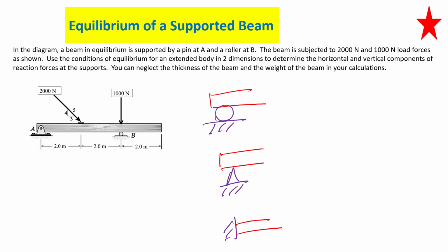Roller support. Roller or rocker. It lets the beam move in this direction, it's only preventing going down, isn't it? So there is a reaction only in the vertical direction for this one. So when you draw the free body diagram, you are only considering the beam or a part of the beam and replacing supports with forces. So this one, when you replace it, just has one force.